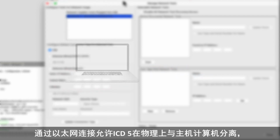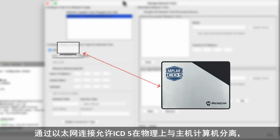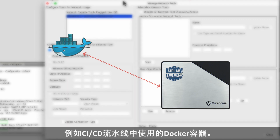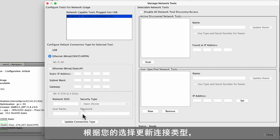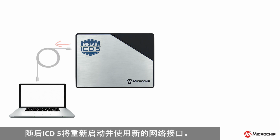Connecting via Ethernet allows the ICD 5 to be physically separated from the host computer, and also permits it to be used from virtual environments, such as a Docker container used in CI/CD pipelines. Update the connection type with your selection, disconnect the USB cable, and the ICD 5 will reboot using the new network interface.